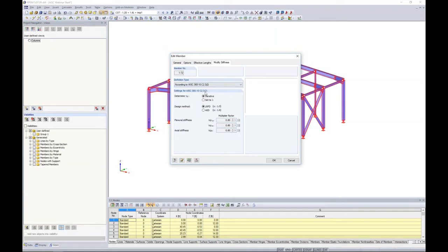So we even give you the code reference. Again, this should look very familiar. This is the criteria that we were just looking at directly from the code. Tau sub b factor, we can either set this to iterative. In that case, it will determine the ratio of my required versus my limit axial compressive forces. Or I can set this equal to 1.0 and then go back in and apply those additional notional loads. Again, I think it's almost easier just to let the program iterate and find that tau sub b factor for me. Now know that this tau sub b factor will only be applied to our flexural stiffnesses, not axial stiffnesses.